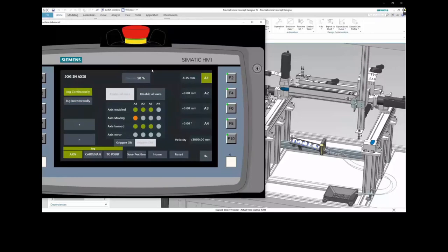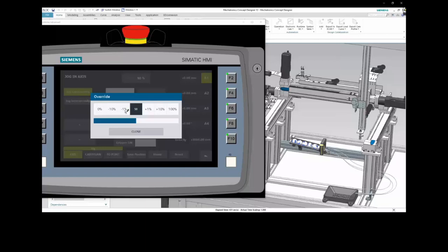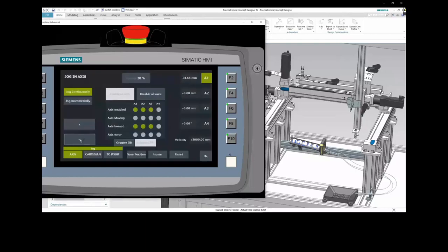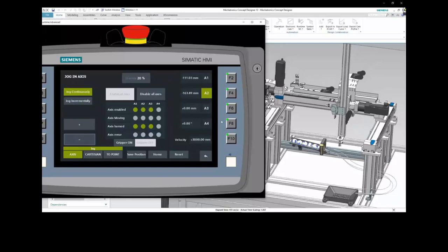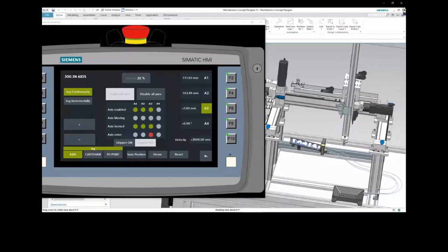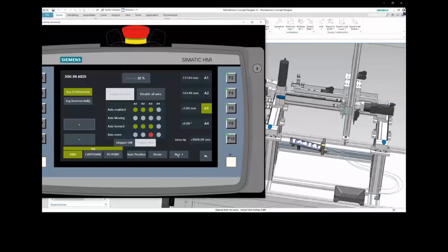And once it's done homing, we can see now the positioning of all of these 3 axes. They would go down to 0, and this means this is all homed now. And then I can start moving the individual axes as well. So if I'm looking at X, for instance, I can see what's the feedback position, where it is, say for Y, and maybe for Z. We also have defined some hardware limit switches in HMI, in MCD, so we can get that as a feedback as well. And if it hits the hardware limit switch, my axis gives me an error that it's gone beyond the limit.